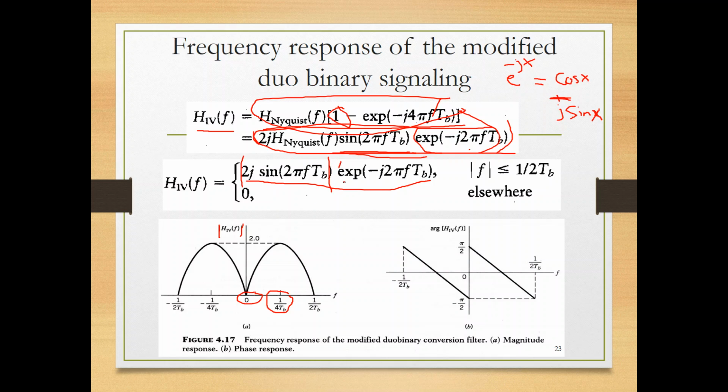This part is the amplitude, and the other part is the phase. When I tell you to represent this complex number in polar form, what do you do? Suppose I gave you this number, 5 plus j6. Represent this in polar form. What do you need to do? I say this is A. This is vector A, or complex number A, 5 plus 6j. I want this in a vector form. What's vector form? It means find the absolute value of A and the phase of A. The absolute value of A, what? Square root of the real part squared plus the imaginary part squared.